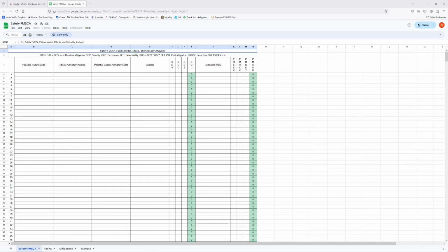Okay, well, I have cotter pins, I have castle nuts, and things like that that hold it in, or I have retainer rings and all these different things, or a press fit, to hold it, as well as a castle nut and cotter pin, and Loctite, and also a mark to make sure that it's not been tampered with. And then you say, okay, I highly doubt this will become undone. So if I highly doubt it will come undone, I give the occurrence a low number. The severity is a very high number, but the occurrence, the probability, is near zero.